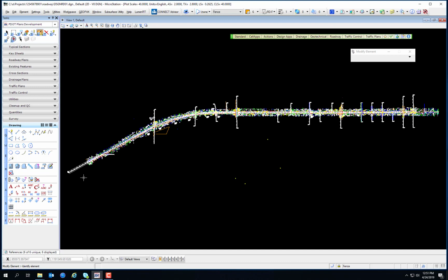In MicroStation, the left mouse button is mapped to a logical button called the data button, which sends a type of graphic input called data point when pressed. So when you hear me say data point or accept or left click, that means the left mouse button. The right hand button is mapped to the reset button, which is used for resetting and for accessing reset pop-up menu and view control pop-up menu. So here we go. There's a difference with the right mouse button. The right mouse button is the reset button, so if you hear me say reset or exit or get out of, that means right mouse button, and that's just a single click of the right mouse button.